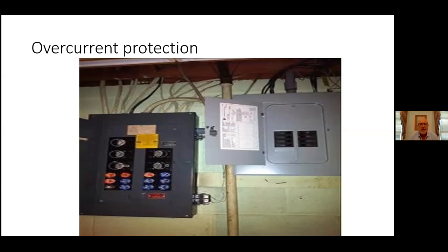And the word got around pretty quickly that if you took something simple like a penny and you put a penny into that slot before you screwed the fuse into it, it would actually keep the fuse from blowing if an overload happened. So basically what you were doing is putting in a penny to put your life in danger, instead of letting that fuse pop and walking to the corner store and picking up another one for about 25 cents. It was very common back in the day. One of the reasons I was happy to get out of that kind of business, because you were looking at a fire hazard at any given time.